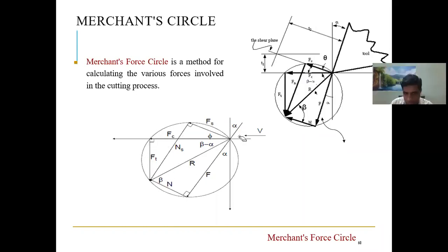In that, the cutting force Fc as well as the thrust force Ft you can easily measure by using one force sensor. The cutting force you can also calculate if you know the strength of the material. So Fc and Ft are easily calculable. And once you find Fc and Ft, the other forces you can resolve and find from this, right? This is nothing but simple sine and cosine resolution.